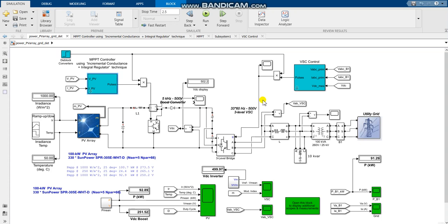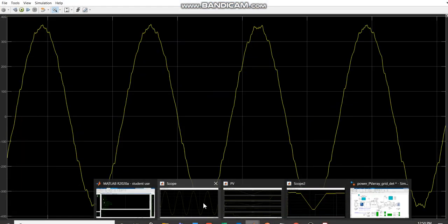Now, voltage amplitude modulation would allow for this by controlling the amount of time during the period that the output signal is actually seeing the 500 volt input signal, and that's done by adjusting the firing angle from the pulse width modulated signals to the IGBT's gates. By controlling when it's on and off using those firing angles, we can get the output signal to be 260 volts RMS. We can see that here using the output waveform for it.